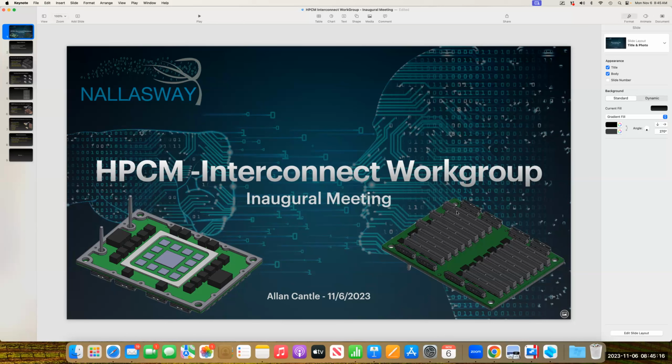We would need some sort of frame. Either the connectors could be manufactured and then assembled into a frame, all delivered in a frame that would then be used in the reflow before being released from it, or it's a separate frame that gets built and the connectors have some features to click into the frame. Those were some of the ideas we were hoping could get over the pin alignment issue. Does that make sense? Is anybody looking at things like capacitive coupling to avoid having to make a copper connection?